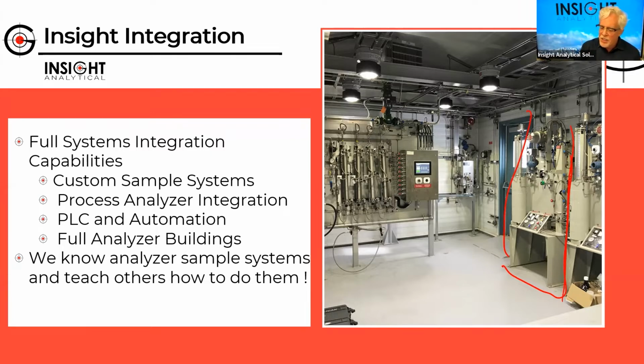There's a solvent flush tank sitting back here. This is a system for natural gas condensate. It can be fairly waxy. And so one of the things we wanted to do to make sure it was low maintenance was give the ability to back flush the optical cell. There's a JP3 near infrared sitting over here just off camera.